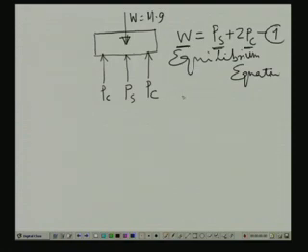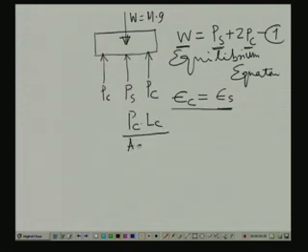So, the strain in the copper rods will be equal to the strain in steel, or the deformation that the bars will undergo. The deformations will be such that the strain in the steel bar will have the same value as the strain in the copper bars, and this leads us to the criterion that if we substitute the values of the strain, which is Pc times Lc by Ac times Ec, where the suffix c stands for copper, it equals Ps Ls by As Es.